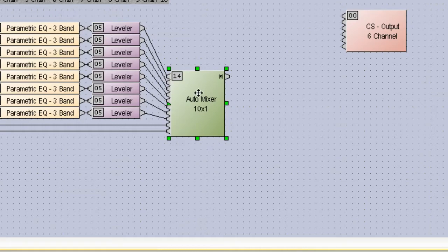Secondly, if we want to combine Automixers using an Automix combiner block, which we'll discuss in a future video, or using the room combiner block, which we'll also discuss in another video, then we will need to connect the output of the Automixer directly to that mix combiner or the room combiner to get that information talking backwards into the Automixer to make multiple Automixers combine and work as if one.